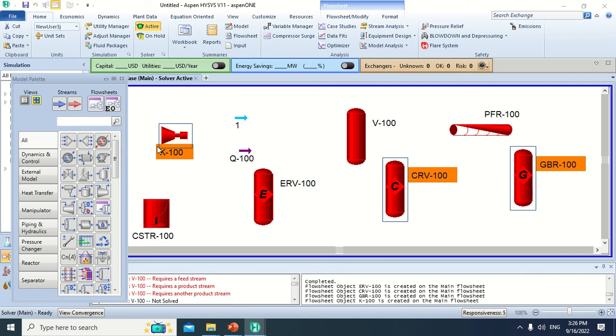This is the compressor. Machines that condense gases are called compressors. Increasing the pressure of gases is possible by reducing the volume, or by increasing the kinetic energy and converting it into pressure. Compressors that work based on reducing volume are called positive displacement compressors. And compressors that work on increasing kinetic energy are called dynamic compressors.